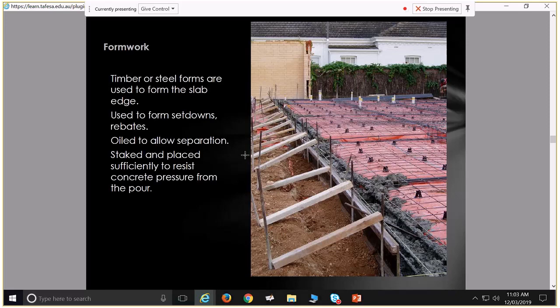Another thing that engineers are going to specify is the lifts. If you're pouring something which is really tall, that concrete, being in a sort of plastic or liquid form, has head pressure. If you think about water supply, if water is up high and it goes to a low point, it provides a lot of pressure. If you've got a tank right up on top of a hill, you get a lot of pressure in your pipe down the bottom. That's head pressure. That's the distance from the top of that material through to the outlet. Same sort of deal with concrete as well.